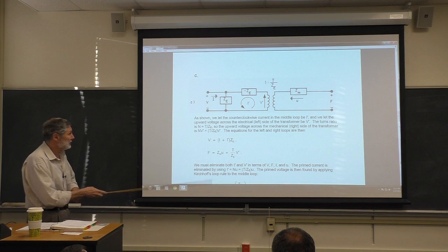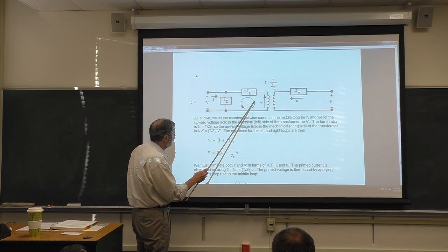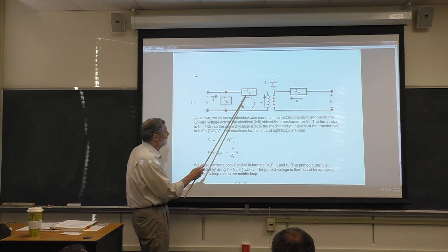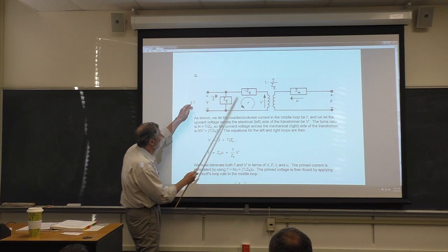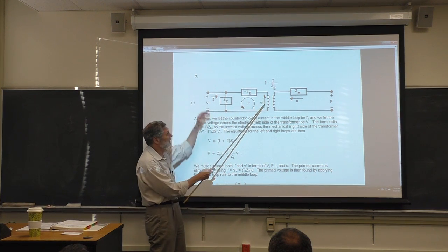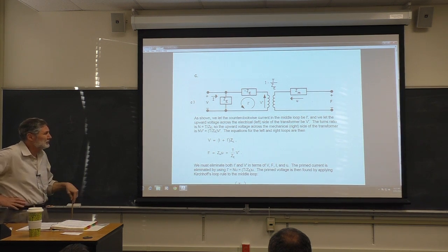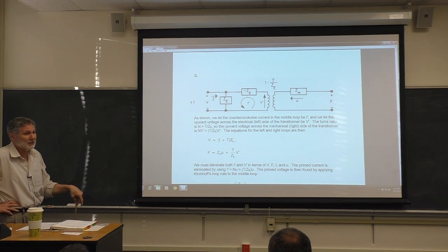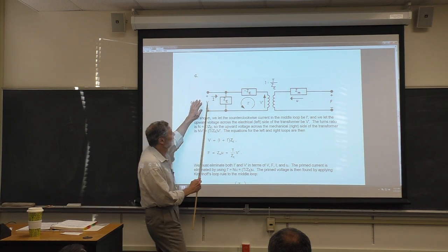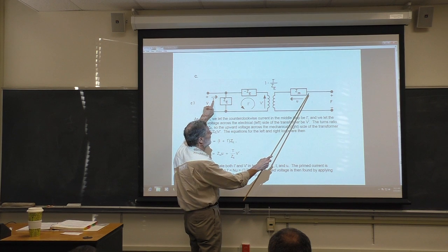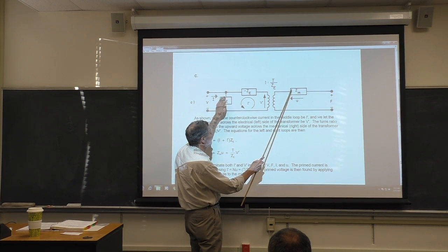So what we have to do here, and I think I mentioned this yesterday or the day before, is assign the usual mesh current here. We're going to assign an unknown I prime there. And because we've got this impedance in the way, this is not going to be V, we're going to call it V prime. We want to introduce these 2 unknowns, which we're going to have to eliminate, because the canonical transduction equations only involve V, F, I, and U, in addition to the circuit parameters.